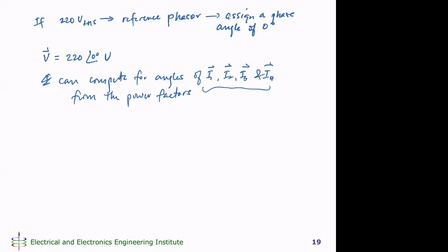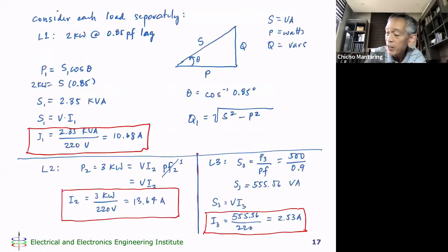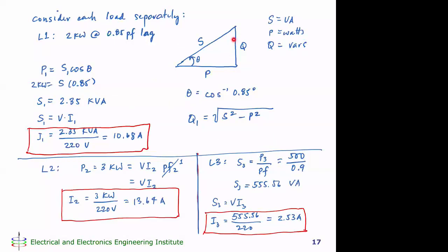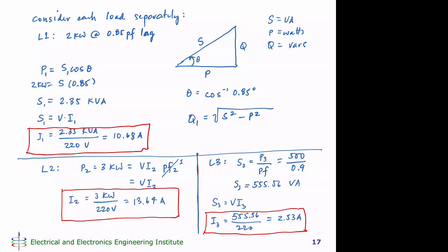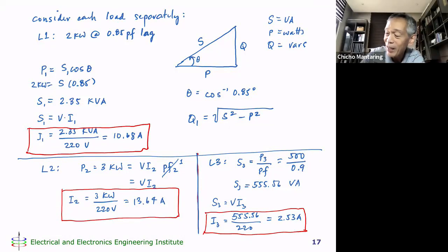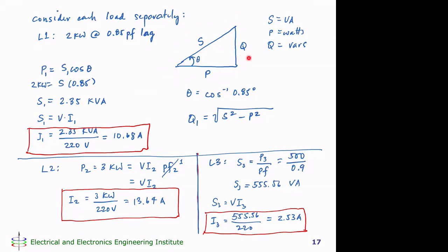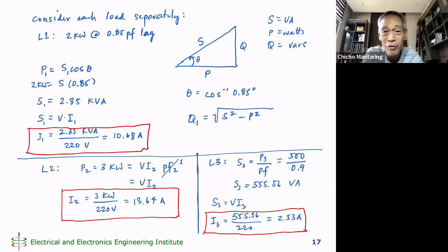Capacitive load, ibabaliktad dapat yung power triangle? Basta capacitive load, you just use the power triangle, and then tandaan na lang ninyo na yung Q dapat gawin mong negative. Hindi na kailangan i-drawing na baliktad. This is for you to compute P and Q from S. Pero pag sinabing leading ang power factor, then you always have to make Q negative.